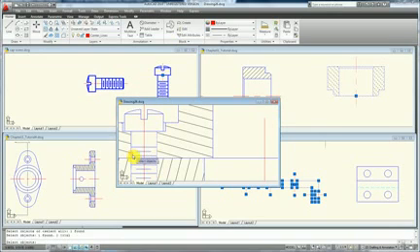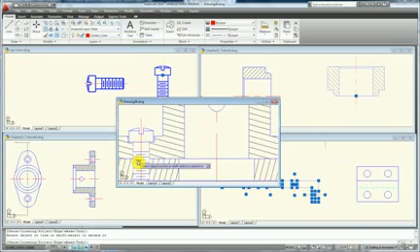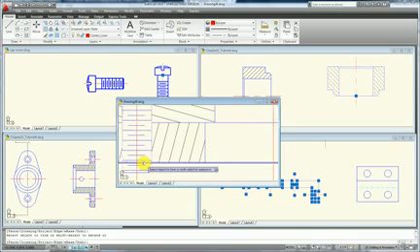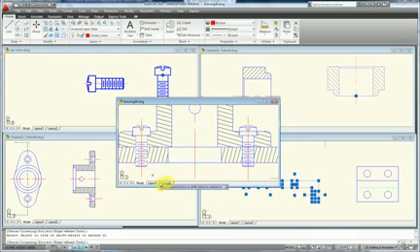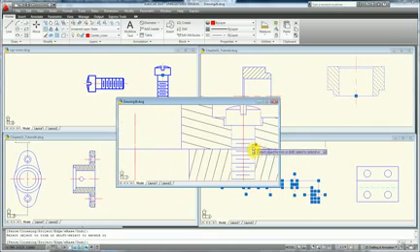Right click and choose that line and this line down here. That way you can see the screw goes all the way through the part. Spacebar, hit spacebar again. I'm going to choose the outside two lines and then these two lines. Right click. I'm going to choose that line that's part of the bearing that goes through the cap screw, as well as this line.